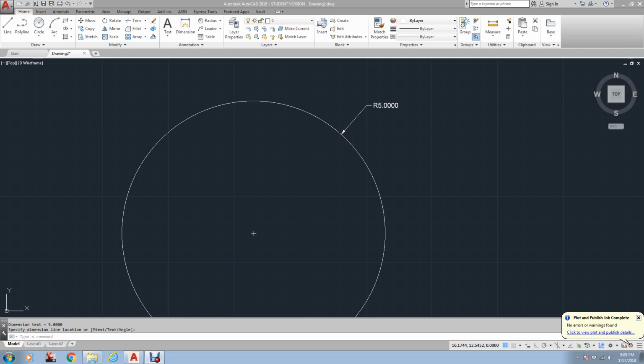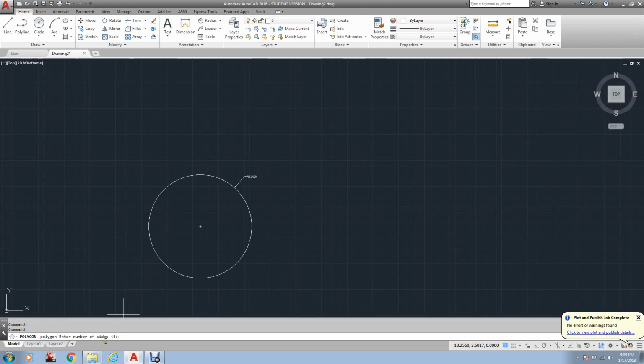And this video will be covering the AutoCAD command Polygon, which, if you look on your screen, actually shares the spot with Rectangle. They do similar things, kind of like Trim and Extend and Fillet and Chamfer. So to make it work, they let them share here. Now, Polygon. One of the first things it asks you is how many sides you want to have. When you create a polygon, whatever number of sides you give it, those will be equal sides.